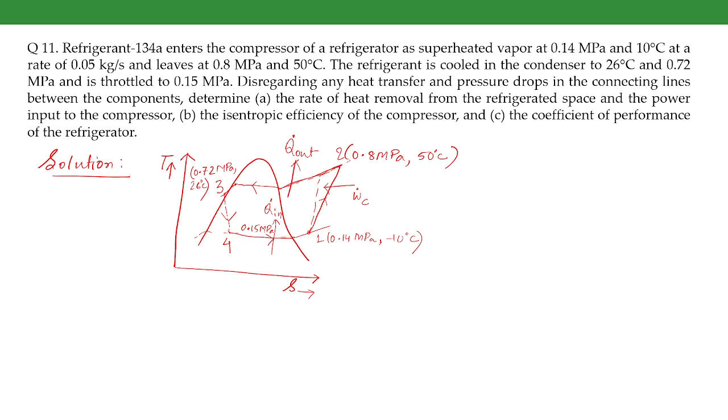So even if it is adiabatic, it won't be isentropic. So in this case, due to this, since the process is not isentropic, there will be an increase in the entropy at the exit point, because the entropy generation term in this case will be greater than 0. So the entropy at the state point 2 will be greater than entropy at state point 1.